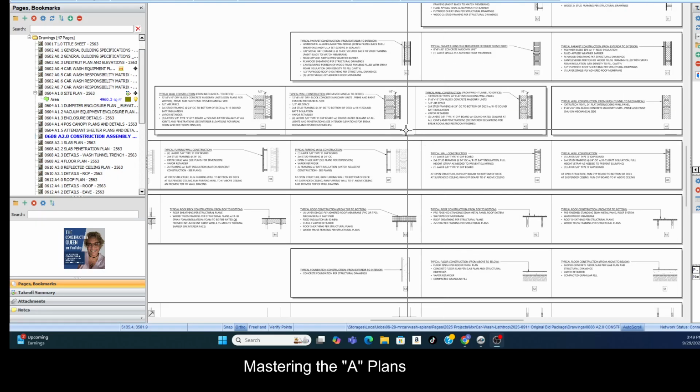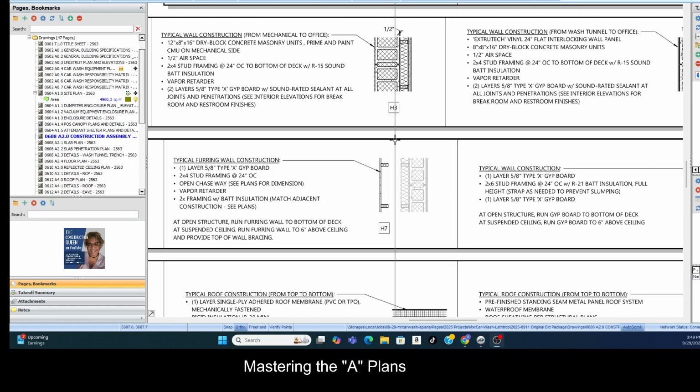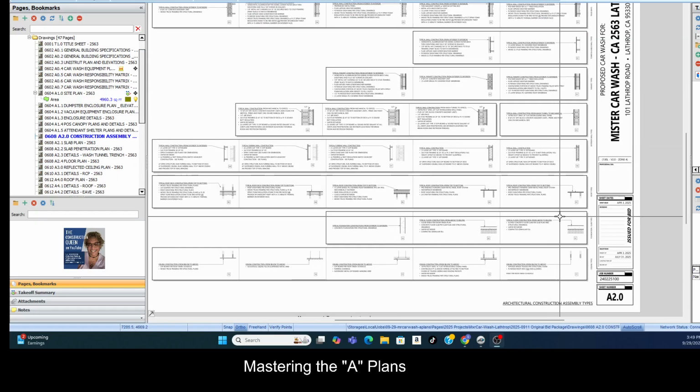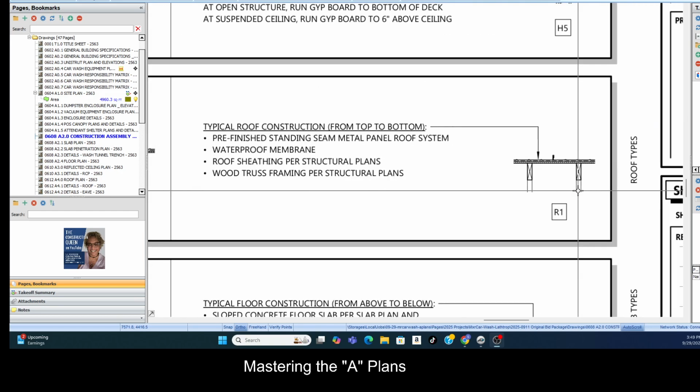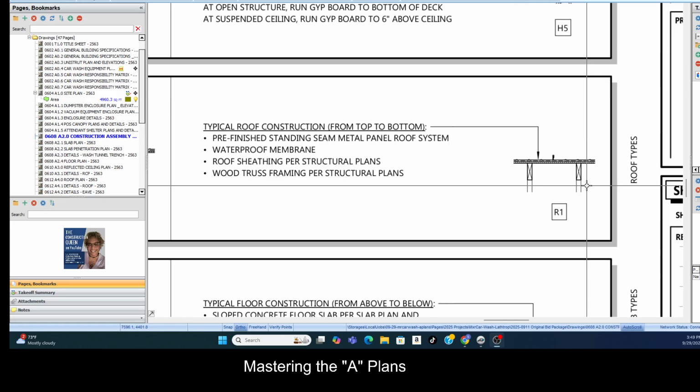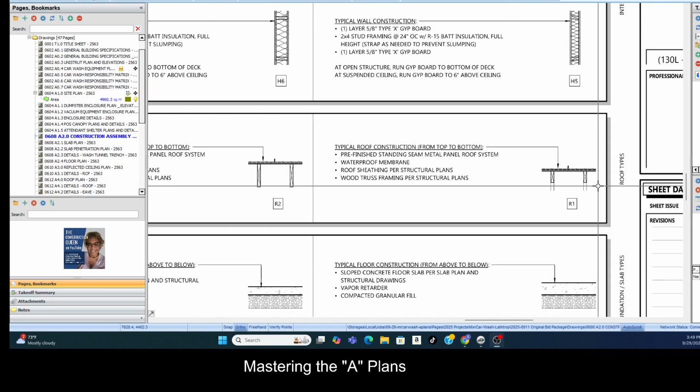As you can see, they have ceiling assemblies, everything. And this is a good sheet. It's really easy when you have something like this to be accurate on what they're asking for. I like it when it's like this because all I have to do is determine how many linear feet, and then I can go line item to line item. Now, your framing, and that's what I like.